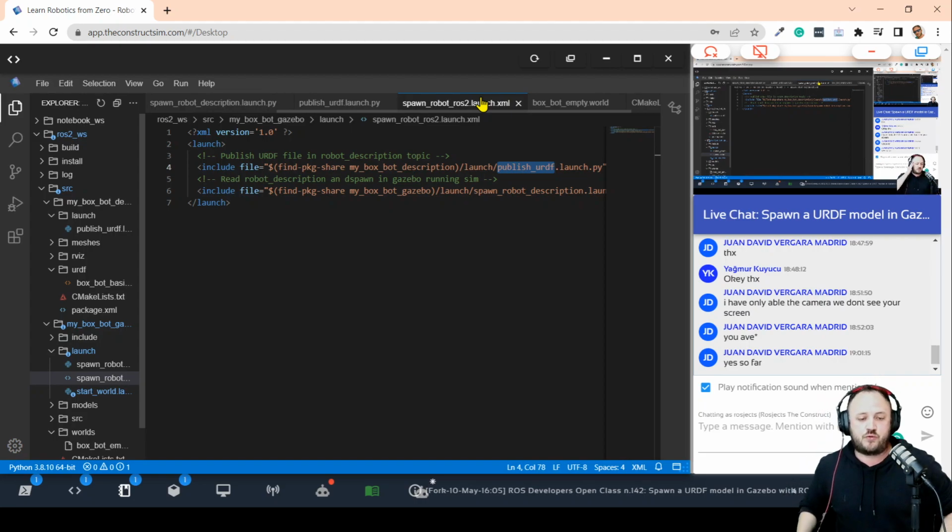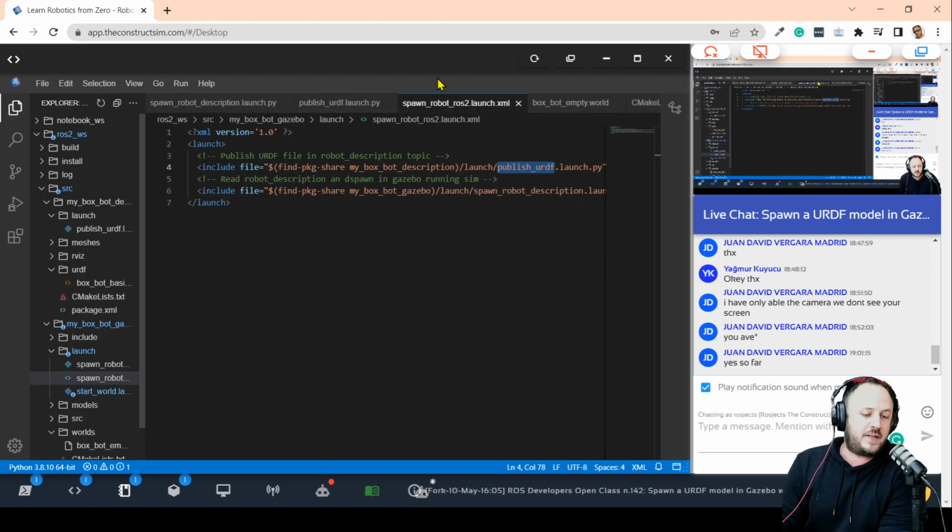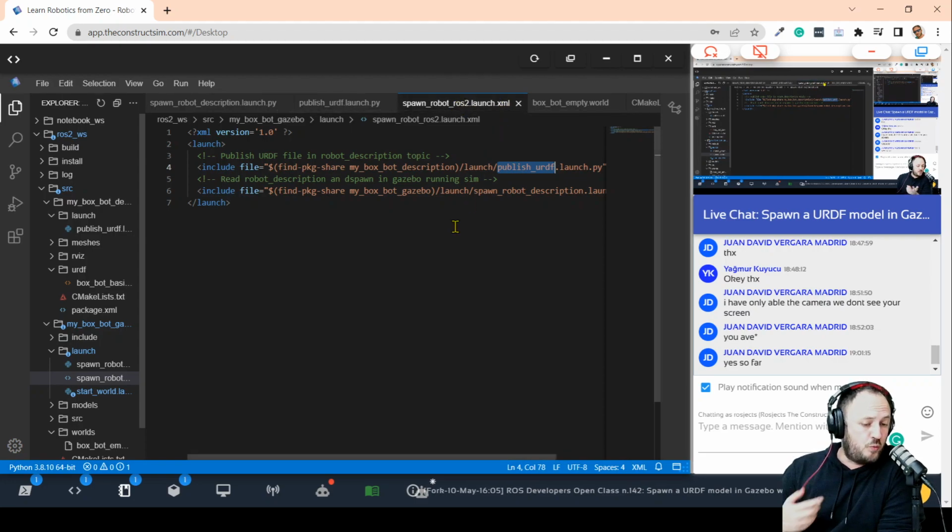Yeah? So very often you are going to find ROS2 launch files like this as Python scripts. In this case, we are creating an alternative version, which is using an XML. Okay? So ROS2 also provides support to create launch files in XML format. And usually it's easier to create them. Also, they are more similar to the ones of ROS1, so it's easier and faster to create them.